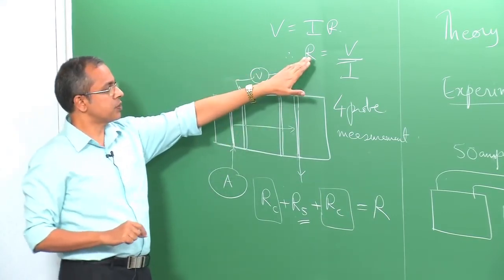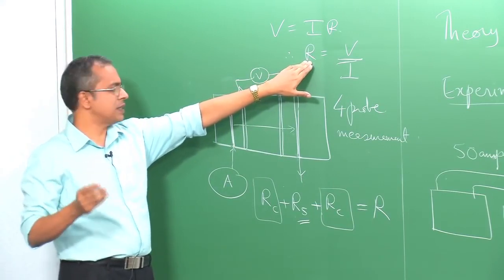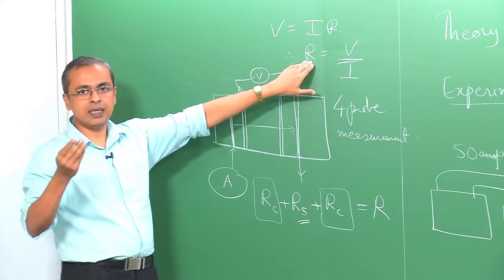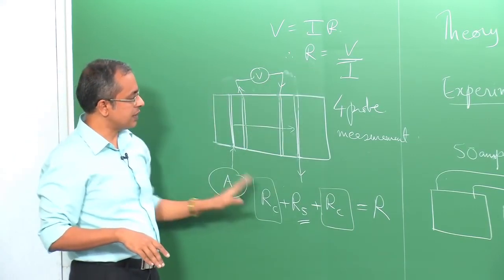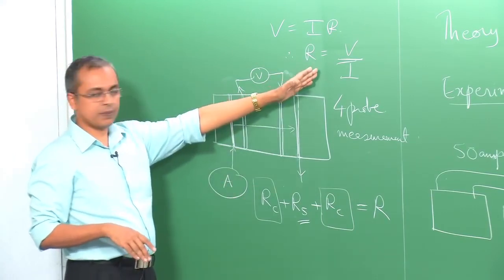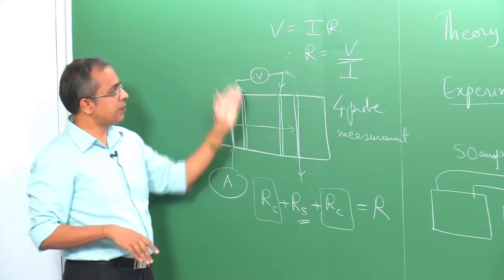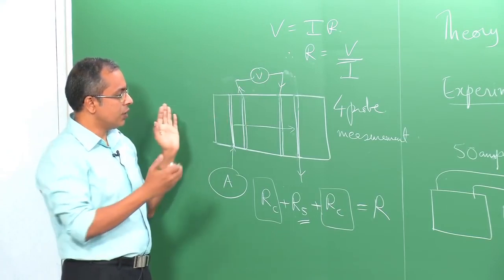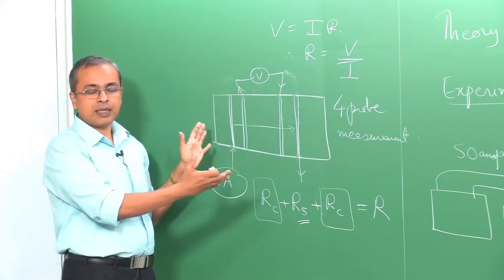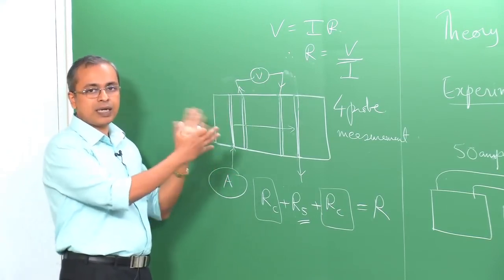If your overall purpose was to get a resistance of the sample, or more specifically you want to get resistivity of the sample, because that would then account for the sample dimensions. I just showed you how the resistivity could be erroneously measured if you had a 2 probe measurement, and can be much more correctly measured if you did a 4 probe measurement. And therefore, again, the way you run your experiment can give you either a wrong value or a correct value.